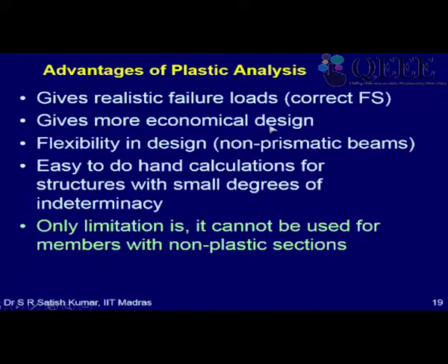It gives more economical design, and it gives a lot of flexibility in design, like I can go for non-prismatic sections, etc. And it is easy to do hand calculations for structures with small degrees of indeterminacy. We saw even a fixed base portal frame can be quickly solved, and it can also be used as a check against some computer outputs.